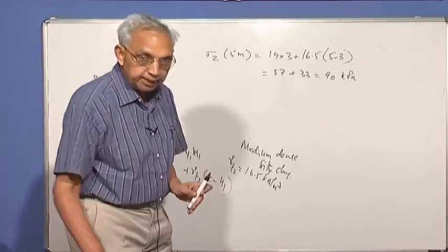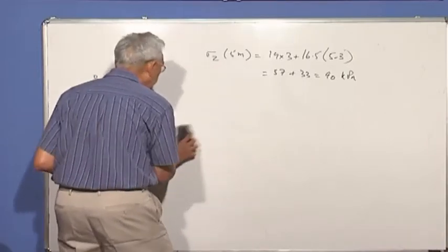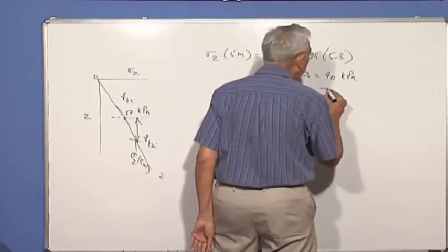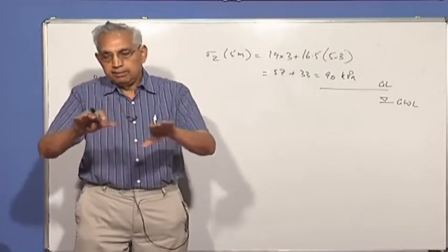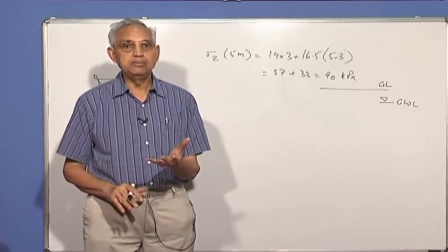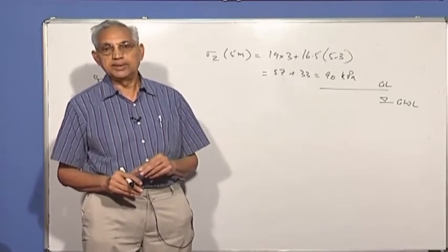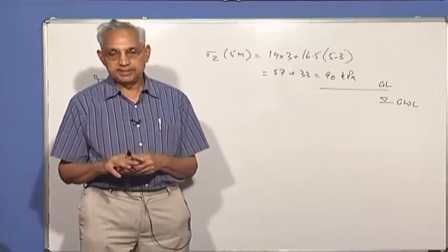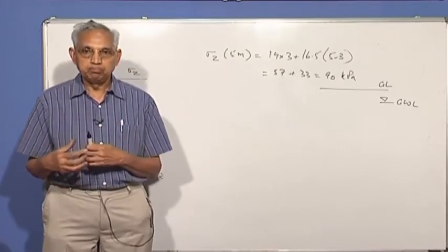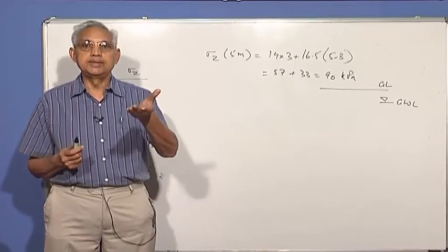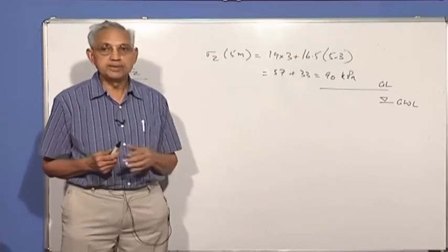Now suppose in the ground there is groundwater level. As I said earlier in one of my lectures, in most places, if you have the ground level, we will have groundwater level. What is groundwater level? It is the level up to which the water will rise within the ground, and if you had a well or a tube well, you will find water at that level. It's very easy to find out. When we do soil investigations, we make a hole 150 mm in diameter, put a casing and wait for a day. If there is a water table, the water will rise up to it, and that is the phreatic surface below the ground level, which we call the groundwater level.